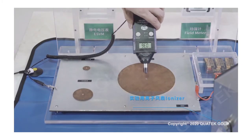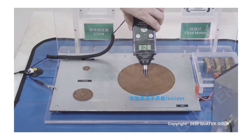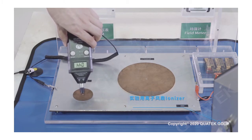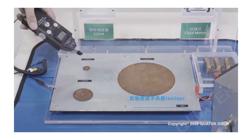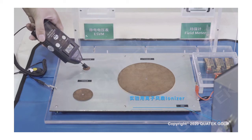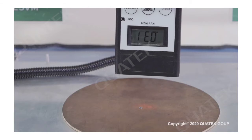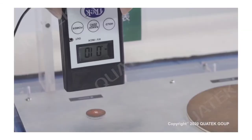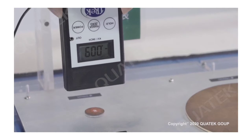In the next experiment, we will place an ionizer on the testing area to simulate the real-time surrounding in the production area. The measured voltage for the TREC 520 is very stable and still around 45 volt even in the presence of the ionizer. However, when we're using the field meter, the measured voltage value fluctuates highly and is unable to capture the actual value. Based on this experiment, it shows that the TREC 520 voltmeter can perform measurement under an ionization area and is not affected by the surrounding electric field.